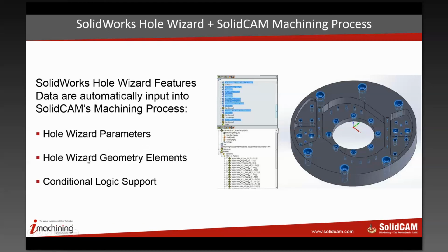Geometries are also available now. Okay? One of the limitations of machine process in the past, especially for drilling holes, was we couldn't come in with a circle mill because the only thing we really had was the center location. Now we have all the geometry entities within the whole wizard. And, again, thanks to our fantastic tech department and development department, we have conditional logic in the expressions. And again, we'll go into detail on that tomorrow in the tech session, but this is really, really powerful.